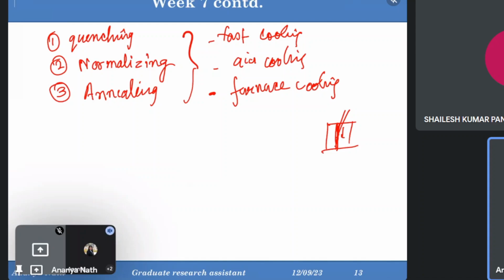So the grains which were forming or nucleating and growing will suddenly be frozen when dipped inside the water. Even in the welding technique, the material is not fully melted, something semi-solidified, and when I dip it inside the water, the grains will be quenched, meaning the grain size will be smaller. If I keep this welded material in the air for a longer time, the semi-solid will solidify with time and the grains will grow with time. So the grain size will be more. It was not a good example, but just to make you understand properly, I am telling about this welding application.